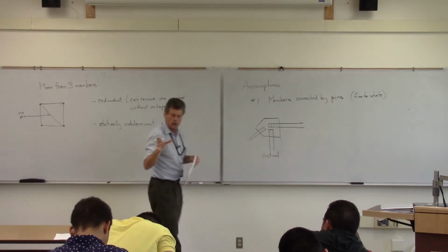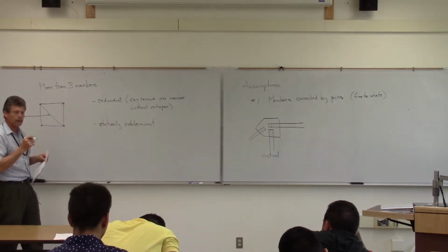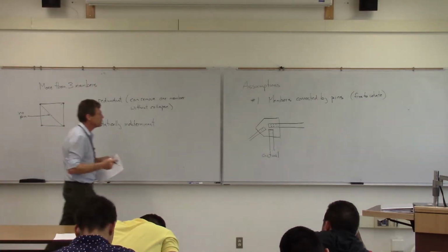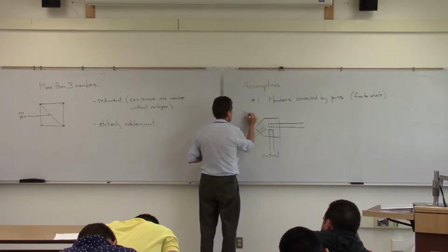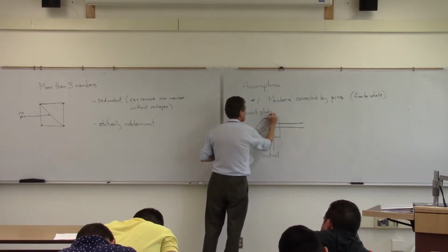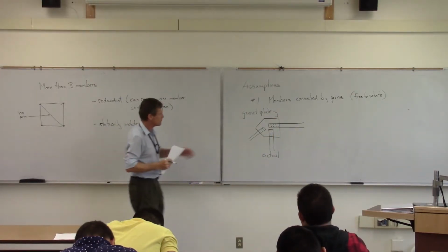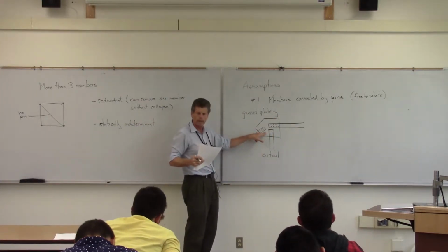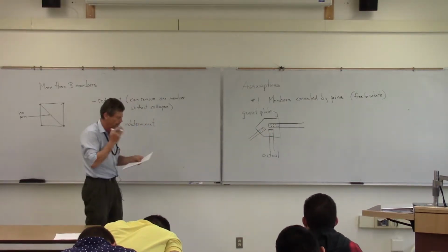The one case we saw in the three-dimensional one in the airport truly had a pin, but a lot of trusses will have a gusset plate that is basically holding the members together. Either they're bolted in, such as wood, or if they're metal, they might be welded in.